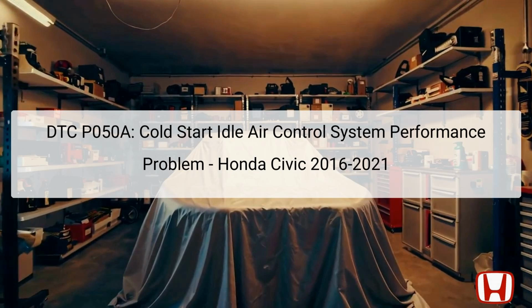Proper functioning of the cold start idle air control system is essential for regulating the engine's idle speed during cold starts, allowing the engine to warm up efficiently. If this system malfunctions, it can lead to issues such as rough idling, stalling, or difficulty starting the vehicle.